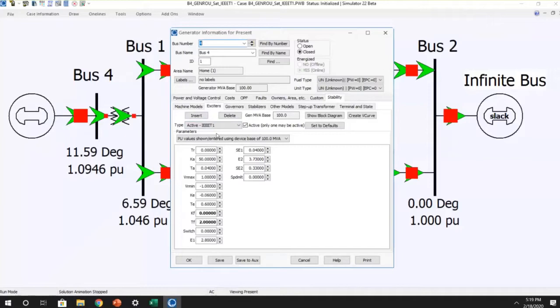One thing PowerWorld does is it lets you know when there's a default parameter value. Whenever we define a model in our code, we set default values for that model. And if the value being used is the default value, we show it in bold. Those are all default, yeah. So if you see a model and nothing is bold, then you know that whoever gave you the data gave you bad data, since there's nothing bold. Yeah, okay, the other way around.